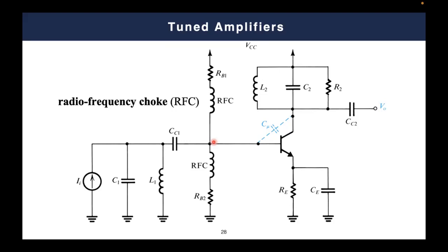But in an AC analysis, the impedance starts to show some value, because now you have L and you have omega, so you have some value for omega L. What if we consider this omega L to be very, very high at the frequency of operation? I know that this amplifier will work at 1 megahertz. So I will choose L to make omega L very high, which means the value tends to infinity, or in other words, an open circuit.